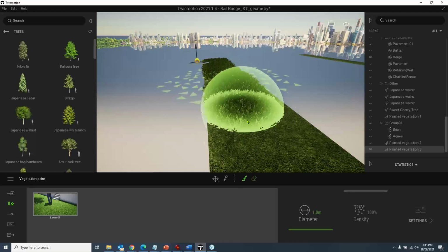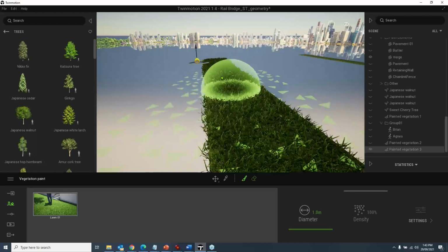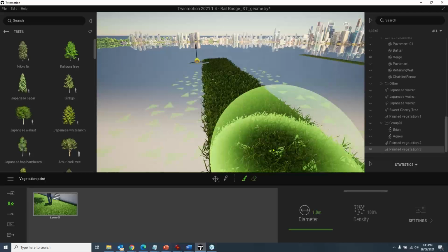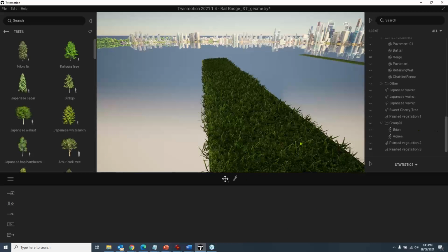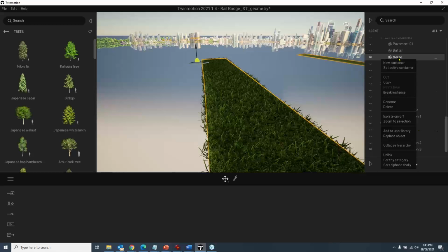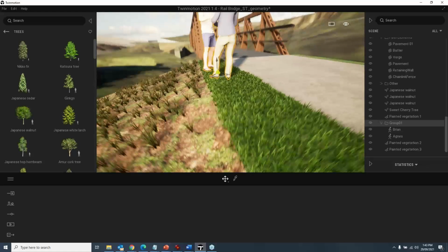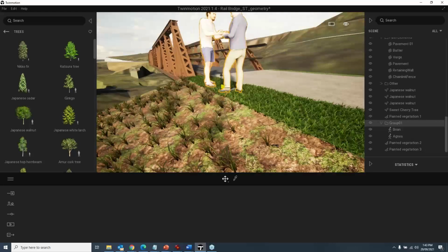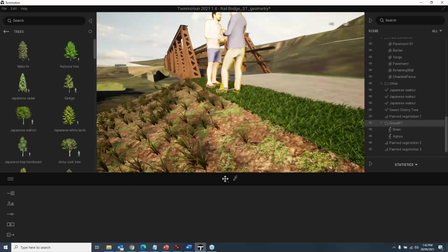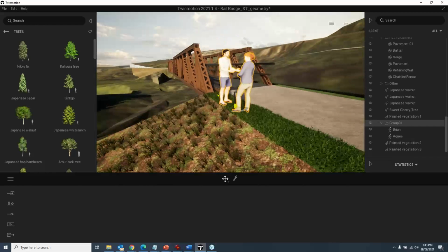And now what I do is just basically draw over this. And I could do a bigger brush and go over the entire whole lot of it. Now, when I turn everything back on, so I'll right click on verge again and turn off the isolation, what you see now is that these grasses have come in. So it isn't just a set of triangles with a texture.